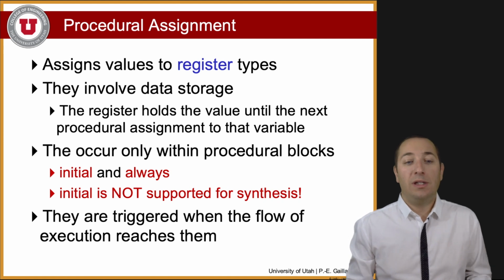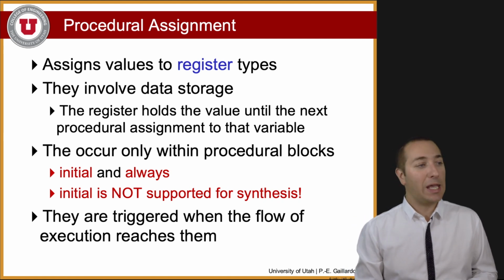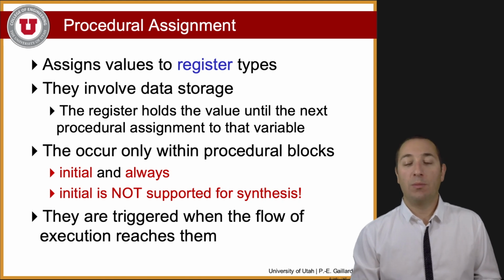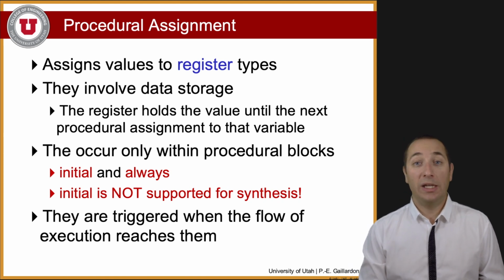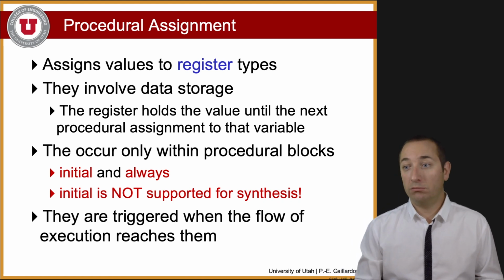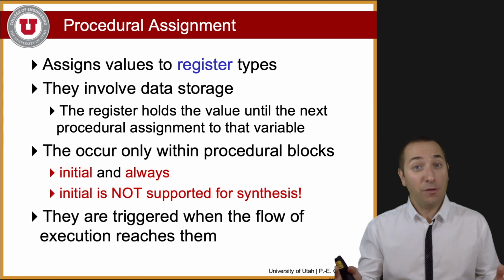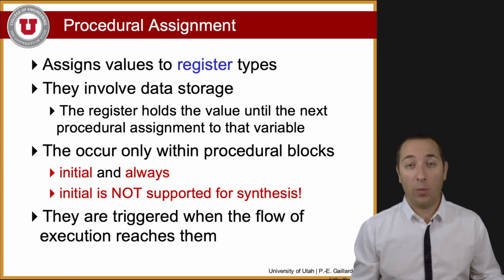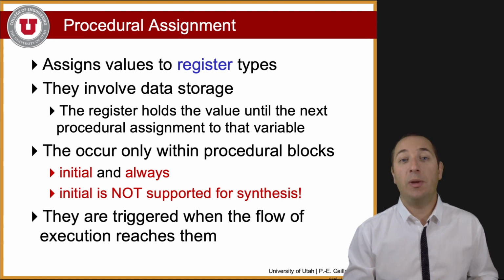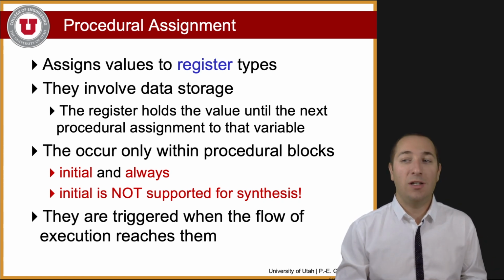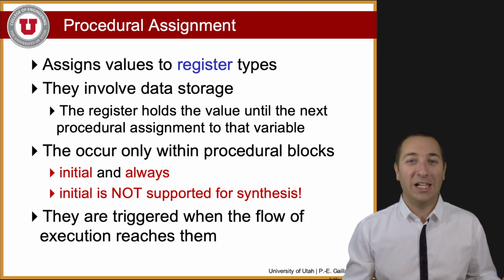Of course, the initial statement tells you, hey, at the very beginning, please consider this value. But the beginning of what? Beginning of the minute? Beginning of the chip's life? Beginning of the power-up? Beginning of time? We don't know. This is why the initial statement cannot be implemented for synthesis. It is used in simulation. In simulation it makes sense because that's the beginning of your simulation.